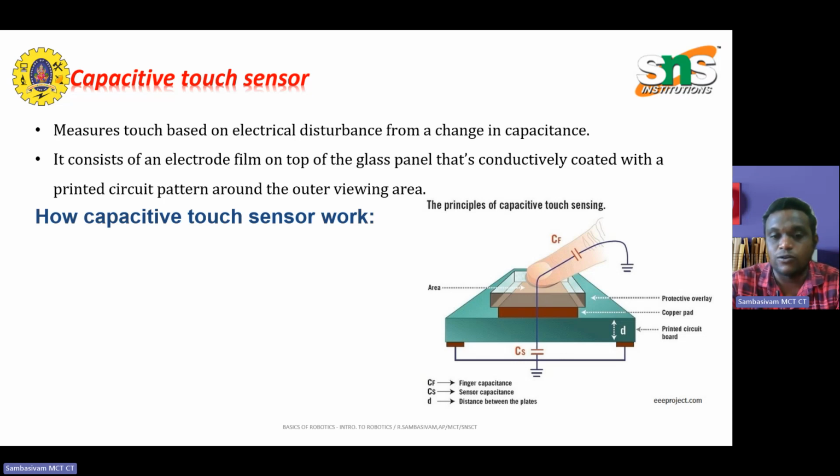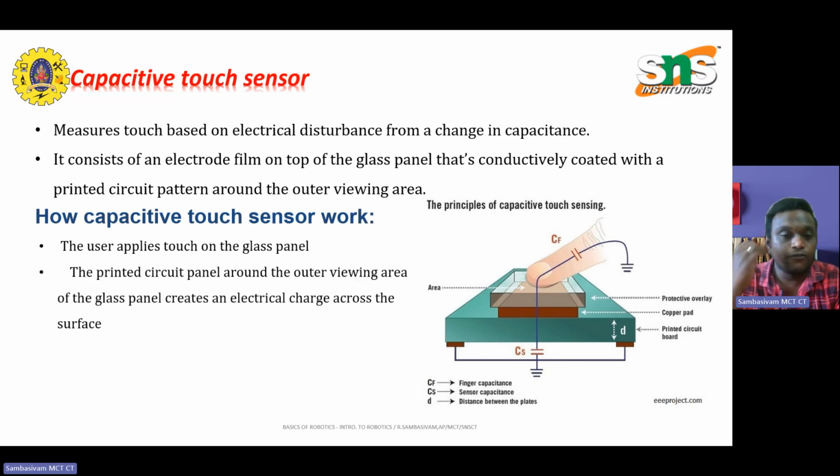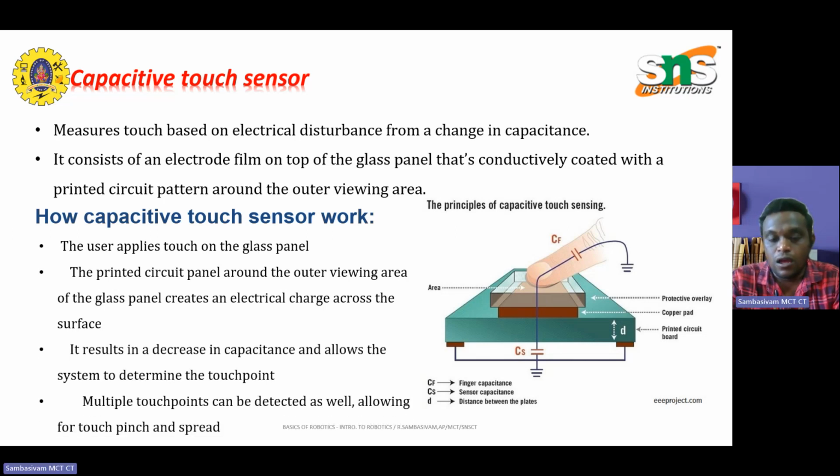In capacitive touch sensors, the electrode represents one plate of the capacitor. The second plate represents two objects. One is the environment of the sensor, which forms parasitic capacitance C0, and the other is a conductive object like a human finger, which forms touch capacitor CT. The sensor electrode is connected to a measurement circuit, and the capacitance is measured periodically. When a conductive object touches or approaches the sensor electrode, it triggers a signal.